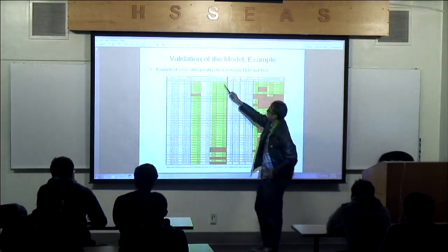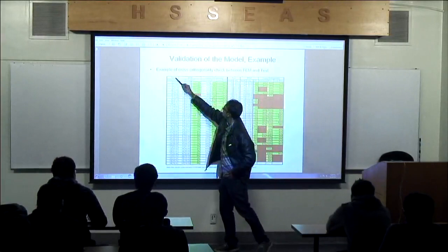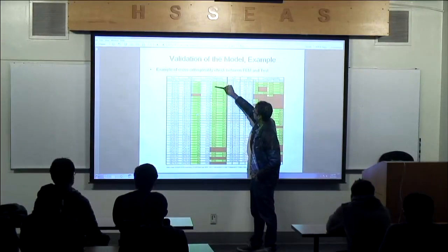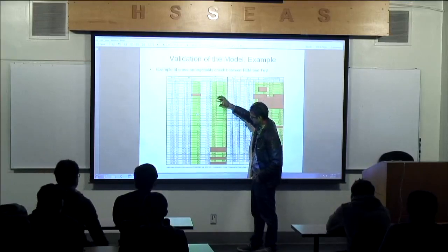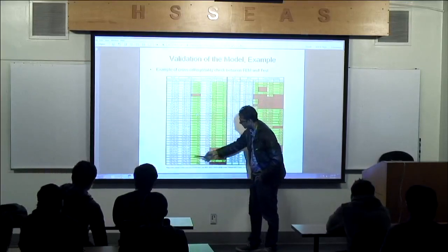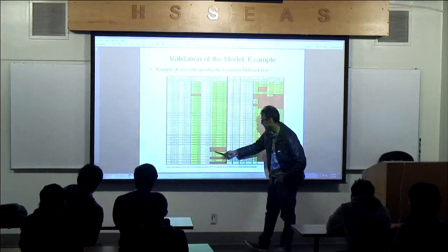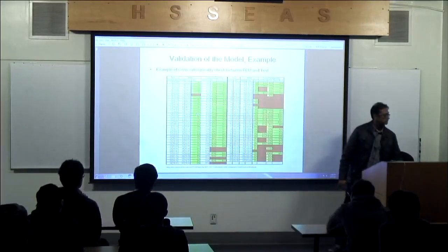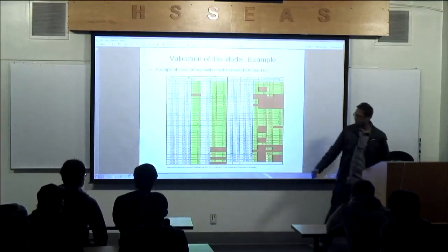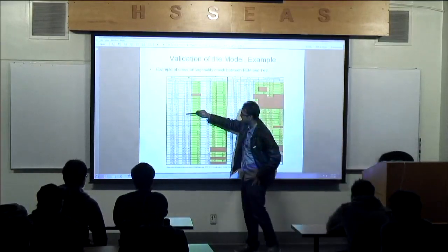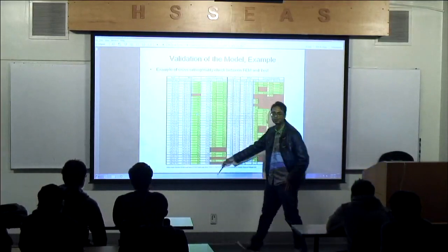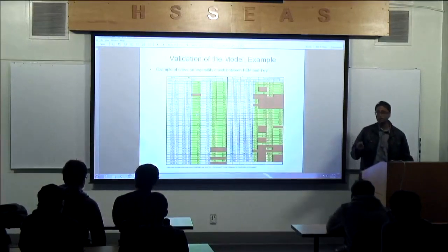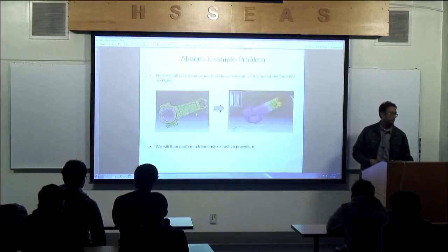So if I do cross orthogonality between FE and test, you can see that the diagonals were close to 1 for the most part. And there's almost no error after 30 modes here. Mode number 30 over there starts to show some problems. Not too bad. At that point you're above 50 hertz. Probably in this project they didn't care about more than 50 hertz. I can't remember from reading the paper, but you guys can go back and read that. No model is perfect, is my point.